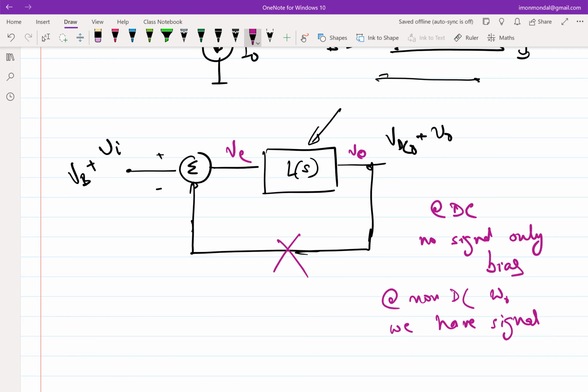at high frequencies. So how do you break anything at high frequencies? You put an inductor, right? So let's put an inductor. In your simulation, you can put an inductor of very large value, whatever is large, maybe 1 kilohenry or something. So essentially say L infinity.